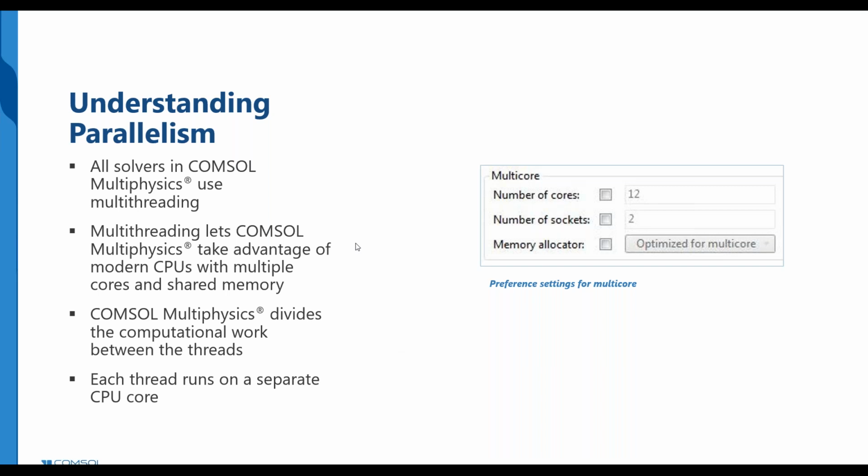Now, next, parallelism is used to handle the limited resource problem, both to solve your problem faster, but also to limit the memory requirements. The first type of parallelism we are considering here is the one you obtain with standard multi-core processors. That is always enabled by default in COMSOL, and you can use fewer cores than are physically available, but then you need to downgrade yourself. By default, we're using all cores.